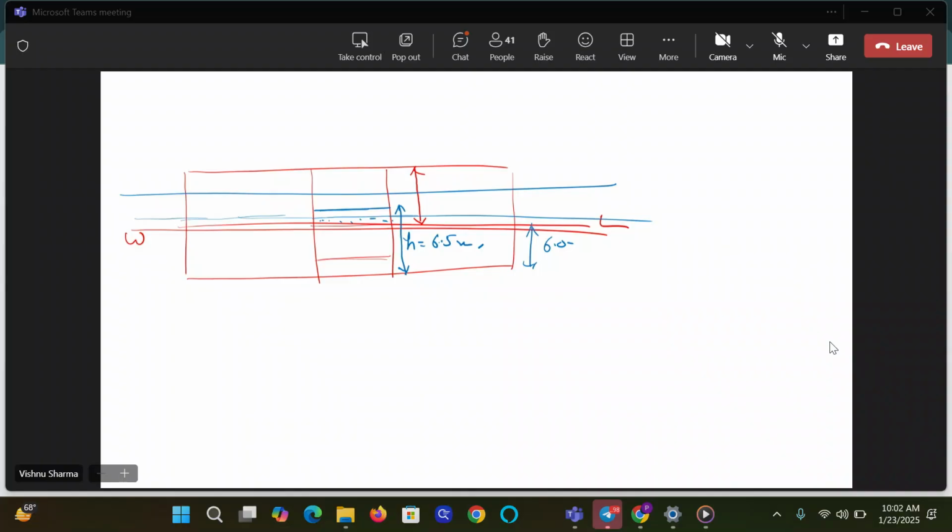Yes or no? So the water plane area will change based on whether the final water line W1L1 is below the watertight flat, in line with the watertight flat, or above the watertight flat. If it is in line with or above the watertight flat, the water plane will become intact. If it is below the watertight flat, then there will be loss of water plane. Have you understood the dilemma, guys? Yes or no? Yes.